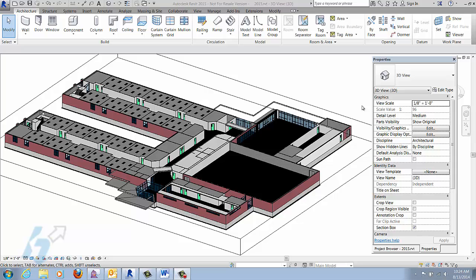Today I'm going to be doing a little video here for you about the forward and backward capability of Revit. And as we all know, Revit cannot be read with a previous version if the file has been saved in a later version. And so one way to get around that, as a last resort, if you really need to get into a model that has been saved in a later version, there is a file format that this can be saved to so that you can open it in a previous version.